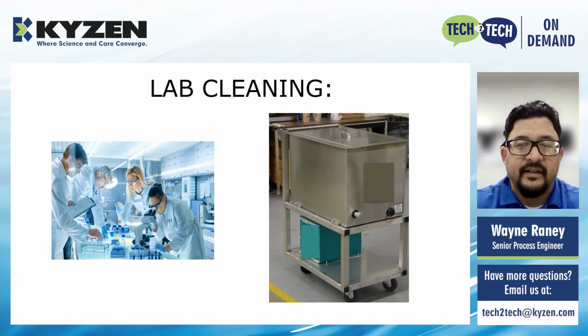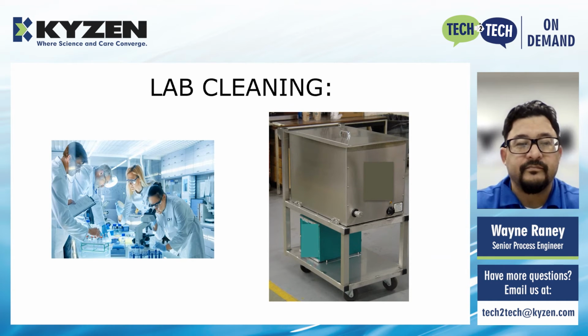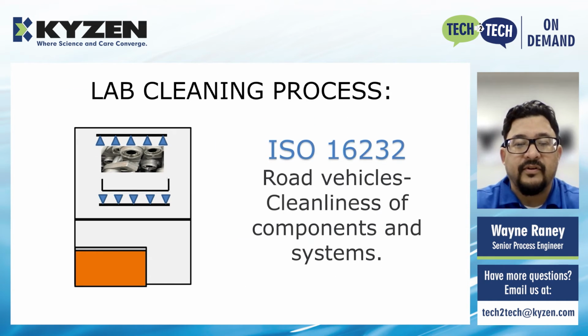So we talked about blacklight testing and surface energy testing for inspection. The next two methods are gravimetric and particle counting. The procedure is pretty similar for both of these. Once the parts are washed on the production line, the parts are taken to the lab where they'll be washed again to gather the impurities from them. The parts go into a lab washer, and the contents are left behind in the fluid.